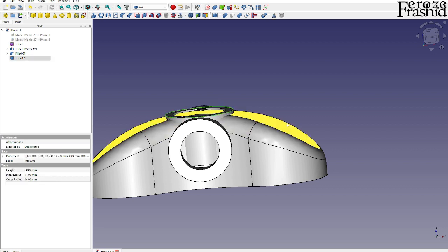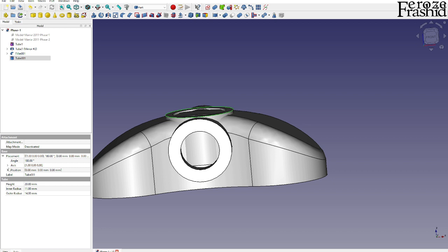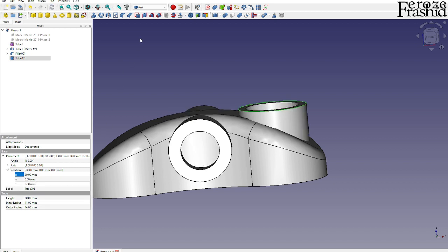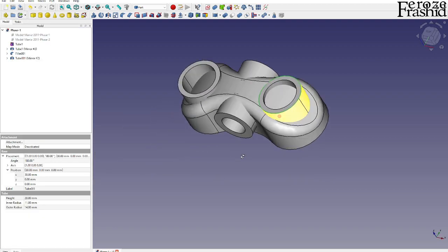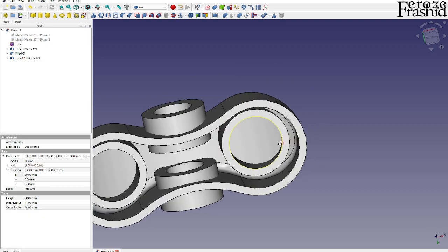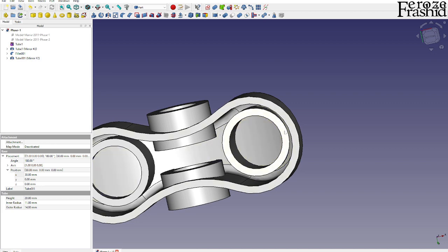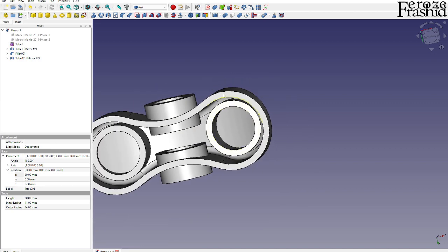And then I want to move it sideways, so that would be X direction dimension 30. And now I want to go ahead and mirror it over on the other side. So if it moves on X direction, it will go on YZ plane as a mirror plane. Okay, now we have these coming downward, and as I said, we'll have to update that height in a minute.